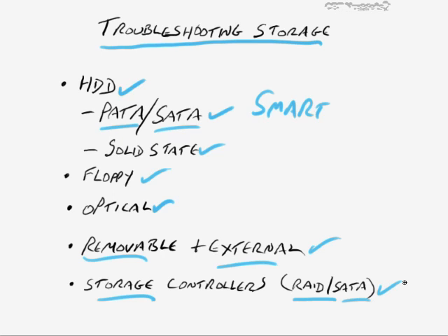And then the other thing would be, it might be a bad controller, just as simple as that. If you have another one that's the same kind of controller, then you can plug that into the computer instead and see if it operates properly. And if it does, then probably the original controller was bad.